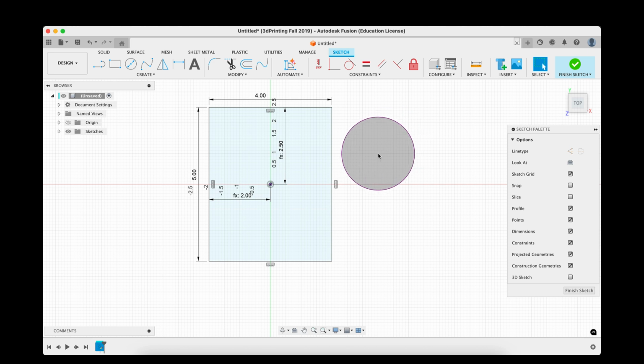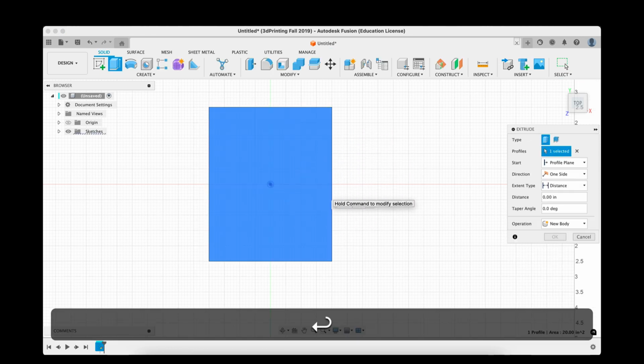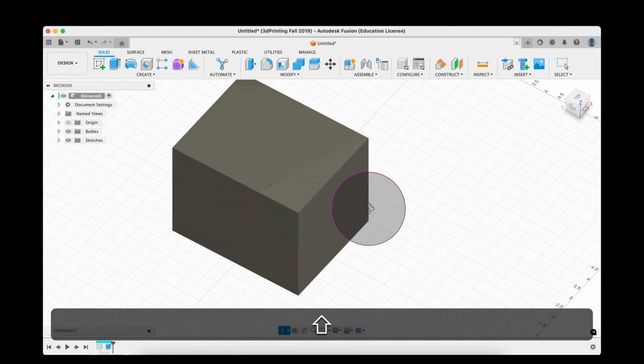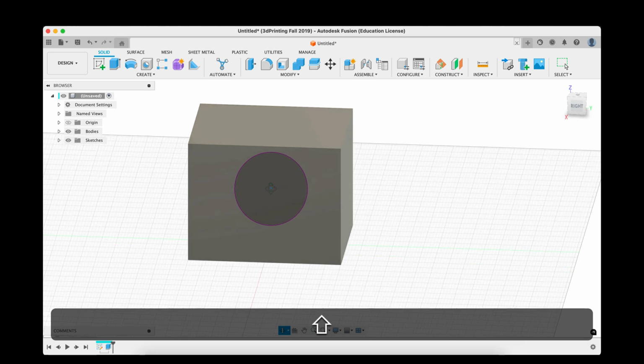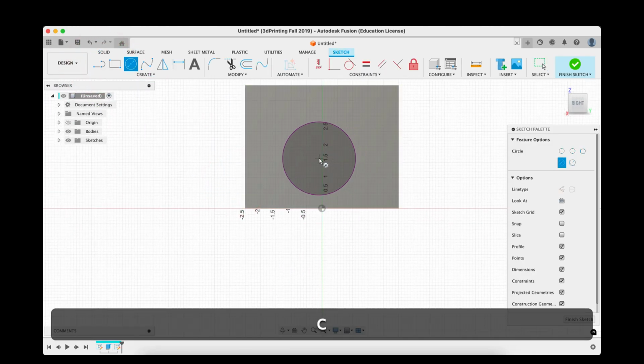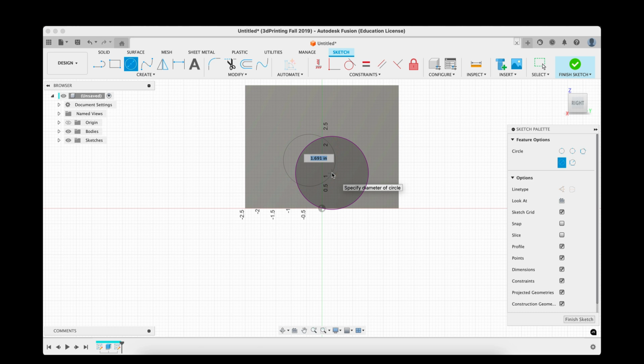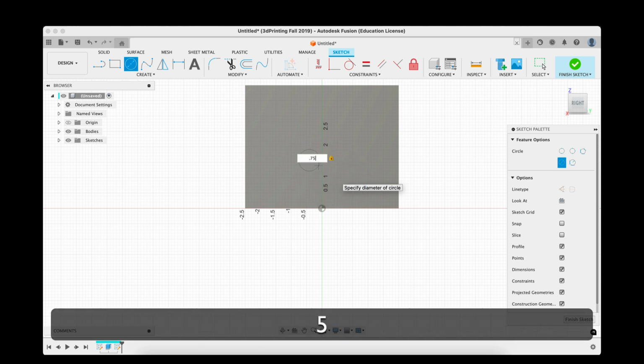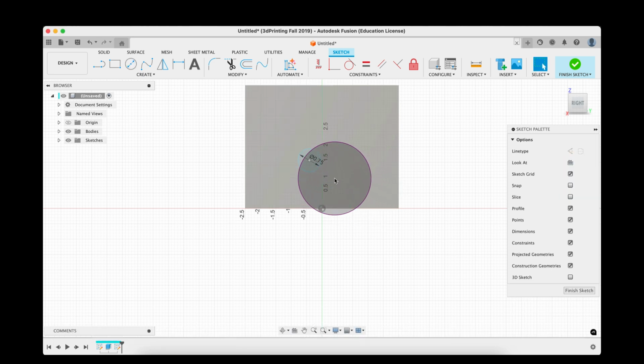I'm going to fairly quickly show a way to use it in something else. So if I extrude that by 4 inches, so I get my cubish thing here, and I'm going to put a new sketch, just redoing the keyhole here, right? I'm going to create a circle, and this time I'm going to make that circle 3/4 of an inch around, right?